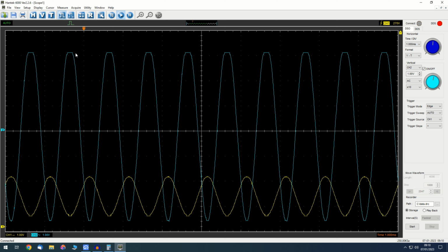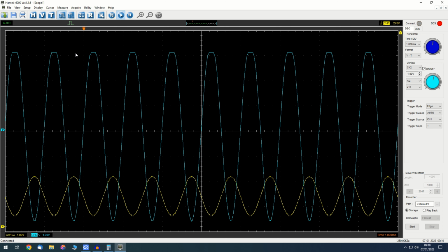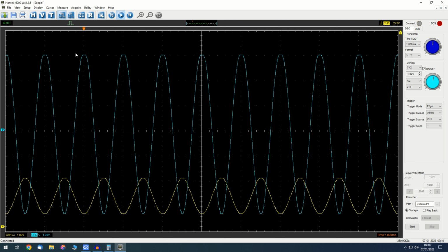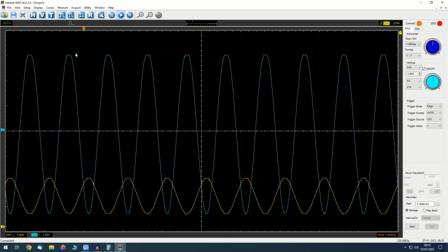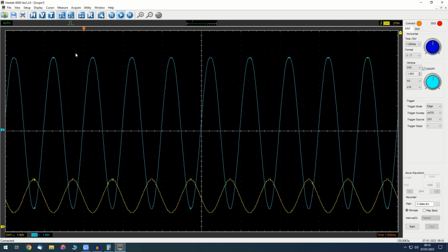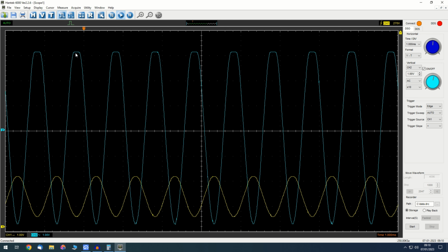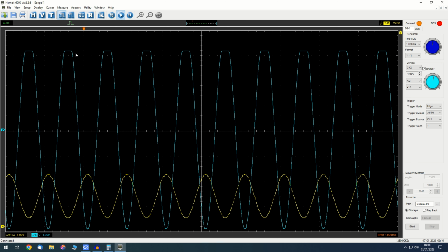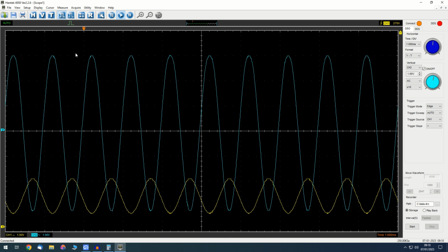If the biasing's about right, it should start to kick in more or less symmetrically. So it's quite a high signal. When it starts to distort, it's 1, 2, 3. It's in excess of 6 volts output swing before it starts to distort. Then it kicks in. It starts to distort at the positive side first. Then you can see it's just starting to clip at the negative side as well. So there's not a lot of imbalance.